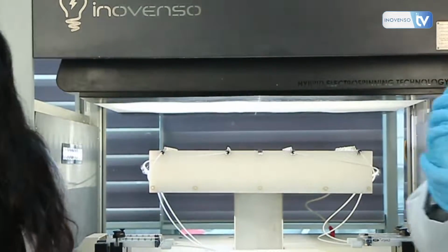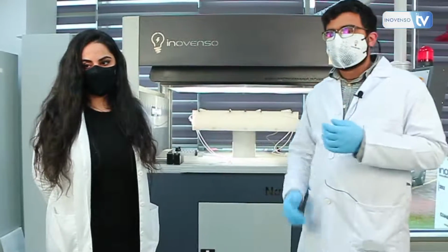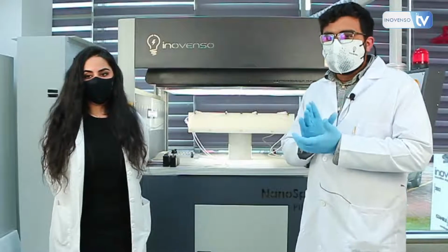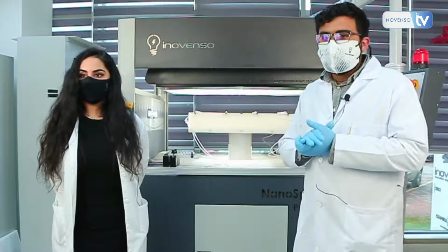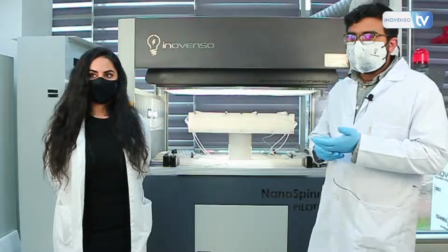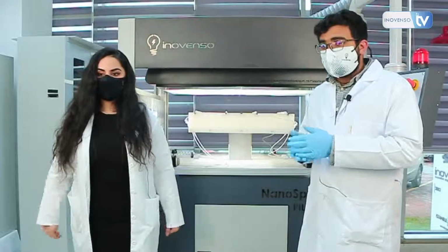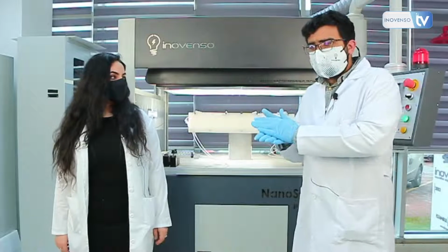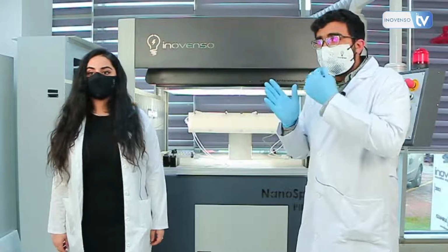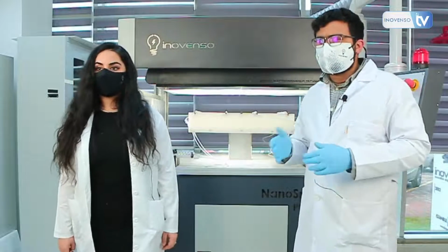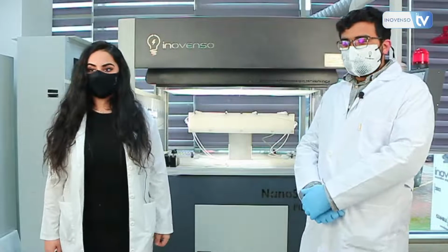So we have a question here. Which raw materials make the active layer nanofiber in liquid filtration and in air filtration? It really depends. There are several, like nylon 6, PAN, polyacrylonitrile, PES, polyether sulfone. So there are many types of polymers that you can use for the functional layer of nanofibers. The main reason is they need to be non-cytotoxic, and they need to have a very thin fiber diameter and good porosity and various parameters like this.